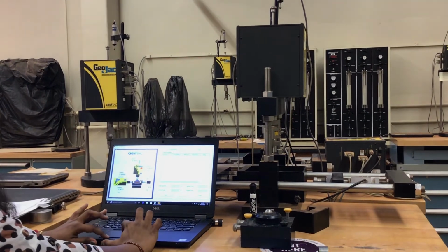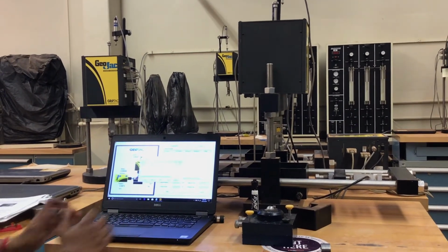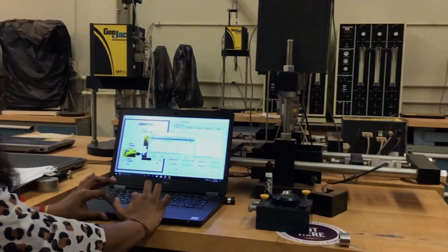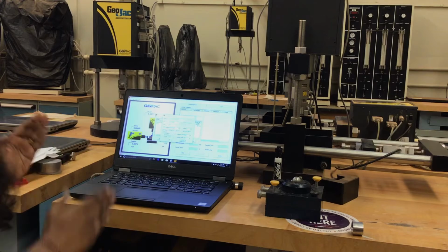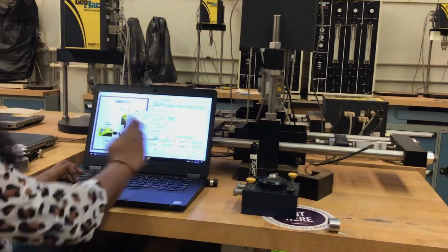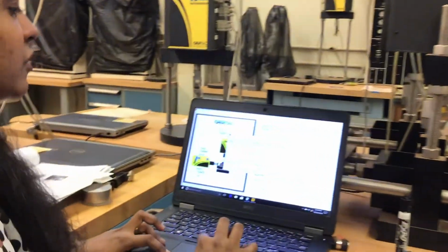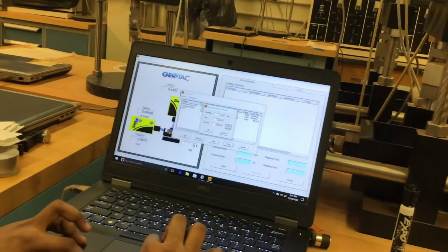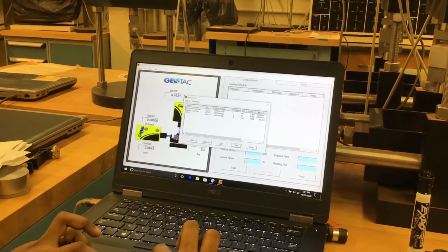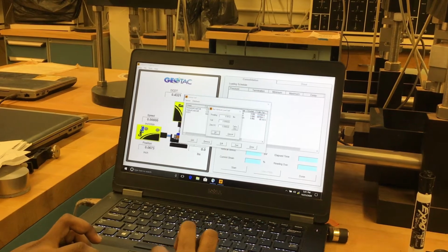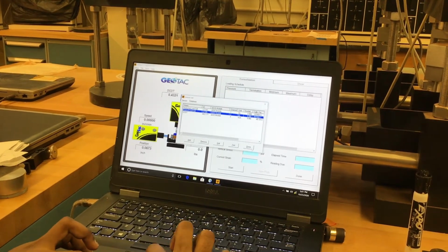So what we have to do first is we have to go to the sensors, and then we have to get all these sensors. Initially it is a must to make sure that the correct sensor is connected by checking their IDs. Then we will be moving for testing and taking zeros for each sensor to make sure no loads are applied. So we will do this for all the 3 sensors and take down the 0 readings.